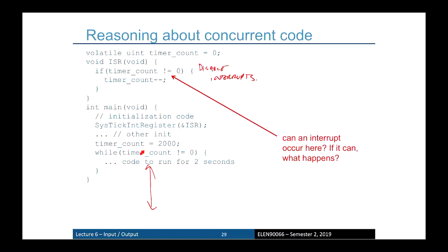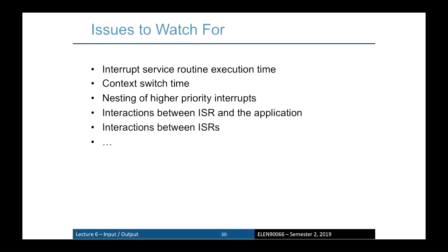So in ordinary C, that might be all right, but somewhere in here this variable's been decremented over and over and over, and you don't check it till you get back to here to check your while condition. So it doesn't matter if that's not equals or greater than. The problem is if there's lots of code in here, you may overrun it. It's a good question though. So this is the problem with interrupts. They're fantastic because they respond straight away to events. But wow, look at all the can of worms it opens up.